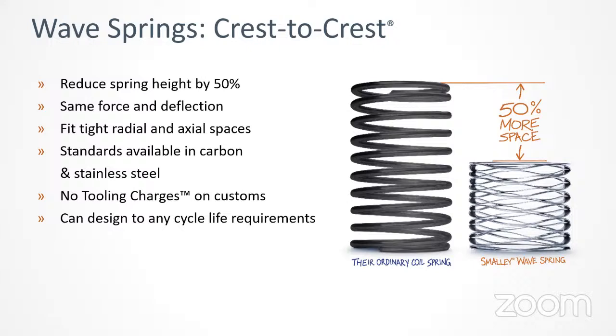You can just adjust the machine and we can manufacture any size, from 3.5 mm body up to 3000 mm body. And this can also be designed to any cycle life, 1000 cycles, 1 lakh cycles, 1 million cycles, or 2 million cycles. We are able to design if the wave spring is operating between two work heights with two different workloads.